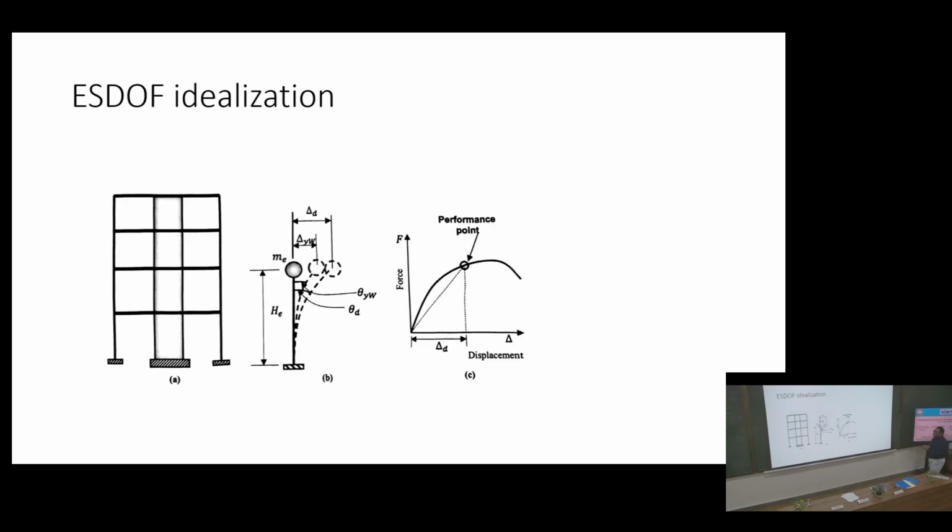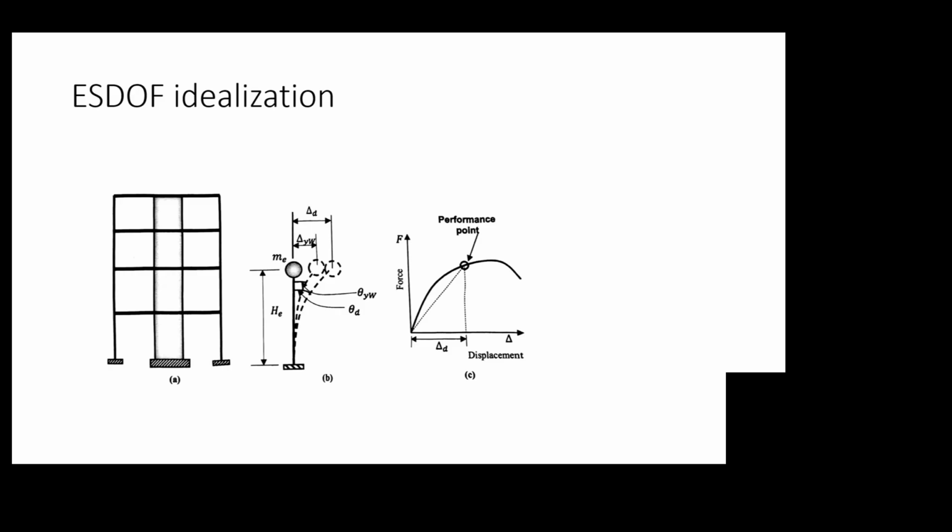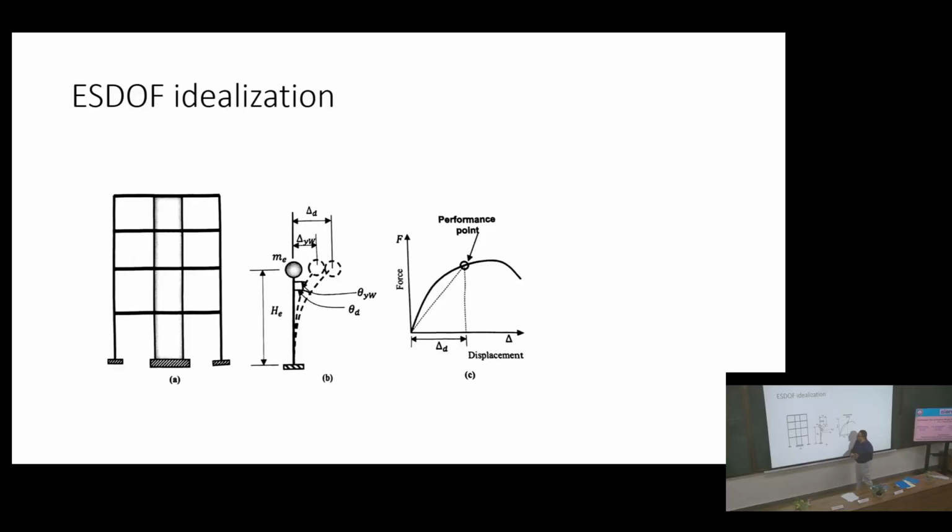So when you have to design this using performance-based design, right, with the direct displacement-based design method, now your multi-degree of freedom system looks something like this. Your SDOF will have ME, HE, same thing. That's your delta D or delta E. That's your design drift. Again, it depends on your hazard level and your performance objective. So let's assume it's 2.2% because that's what the example we did.